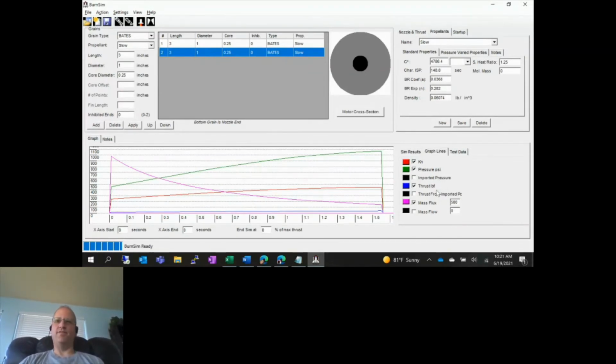Techniques for doing that involve explosively opening a case to try and extinguish the burn partway through, which is difficult. The reasoning is they look at the expected burn, how much of the propellant was consumed versus how much is actually consumed, and use that to figure out how much erosivity is going on.